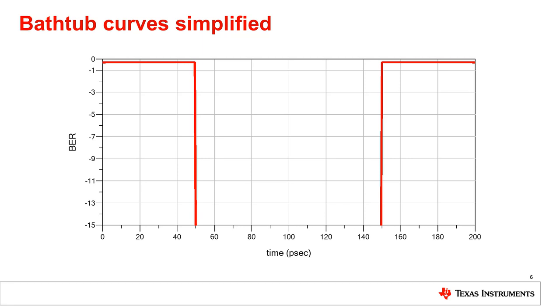You can notice that the y-axis of the bathtub curve shows the BER in a unique way. Most commonly, it is expressed as the exponent of the calculated BER. Using the bathtub curve, it allows the user to understand what level of fidelity is achieved in the system across larger and larger chunks of data. An ideal bathtub curve can be seen above.